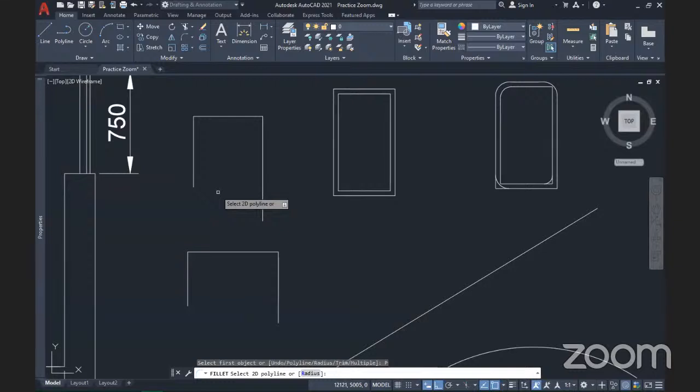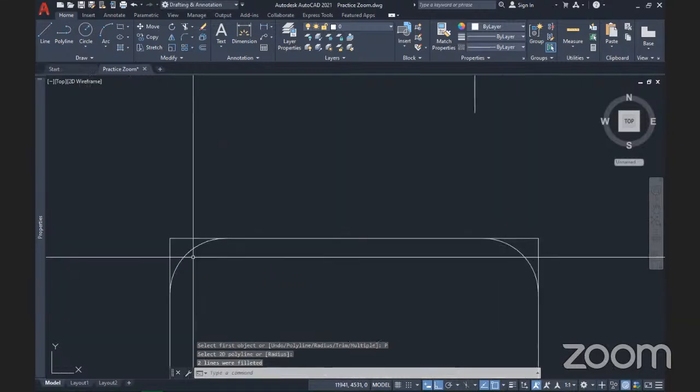It means that if you select the polyline option, you're telling the software that all the corners are assumed to be joined together, and I want to fillet all the corners of that particular object at once. So you do that, you select the object. Now, just notice something. For the line command, I cannot fillet all the corners at once because this is actually drawn using the line tool and not the polyline tool, so it won't work on that. But look at it for the polyline tool. If I just do that, you see, it filleted every other part.